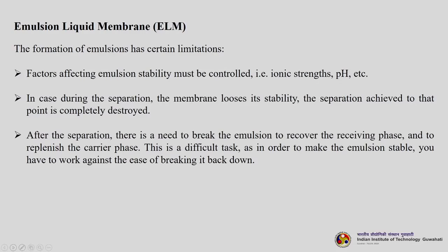After the separation, there is a need to break the emulsion to recover the receiving phase and to replenish the carrier phase. Now, this is a difficult task, as in order to make the emulsion stable, you have to work against the ease of breaking it down, because many times you are supplying stabilizing agents such as certain surfactants to increase its mechanical strength. Now, you want to break it. So, you are going against the entire forces of whatever is present. So, it is a tough task basically.